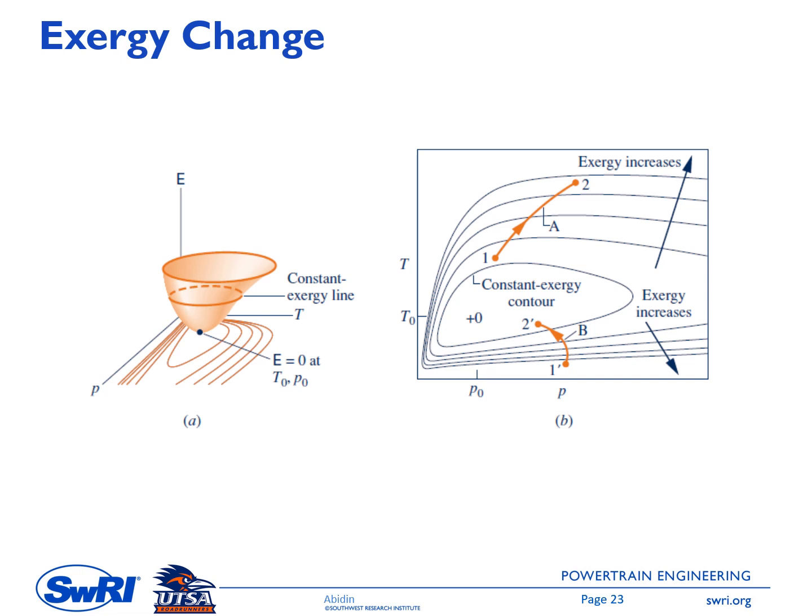Okay, this one is the schematic to show us how the exergy changes from one state to the other state. On the left side, we have a 3D schematic with 3 axes. The pressure axis here, the horizontal one here is the temperature, and the vertical one here is the value of the exergy. As you can see here, we have a point with the black dot. I believe this is the dead state. At this point, the exergy is 0.